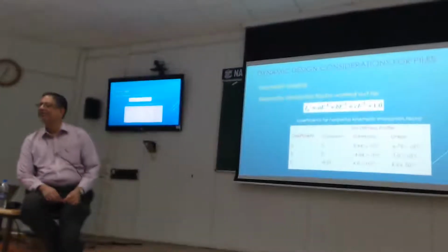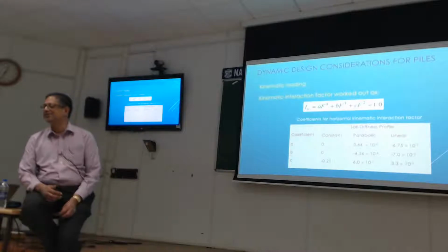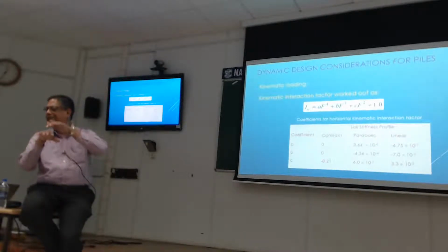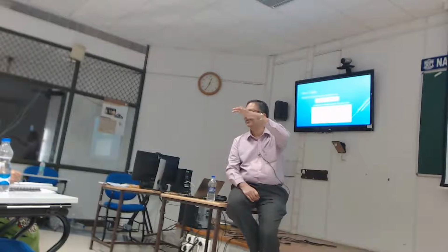Yeah, liquefiable soils are troublesome, but not so much just the liquefiable soil. Where you have lateral spreading with a non-liquefied crust on the top, it can create enormous loads. So that's one situation where kinematic loads can dominate. Also, think of the structure as well. As I said, don't think of just the piles. Let's think of what they're carrying at the end of the day. If you have a structure which is quite light and flat, not high, right?